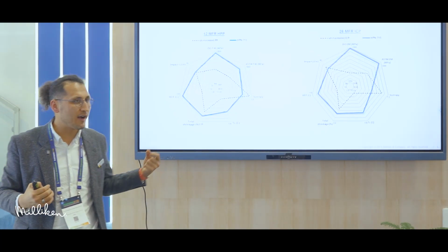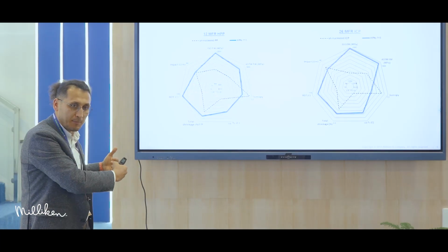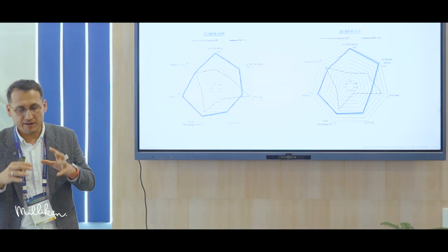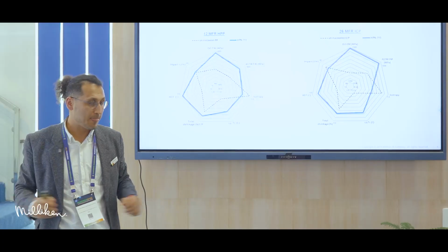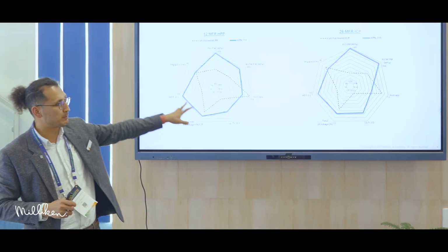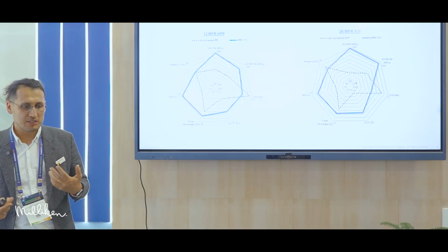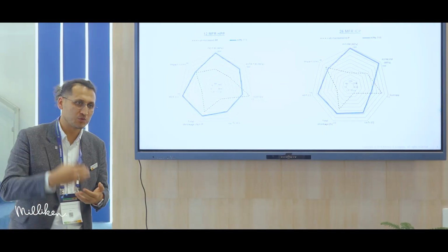Sometimes you have a very high crystallinity, but some other parts, like shrinkage or some other things, are not balanced, because it is very difficult to have one nucleator that is good in everything. But especially in this case, I'm taking the example of, most importantly, the customer, when talking about stiffness improvement, they are talking about stiffness improvement without losing impact.